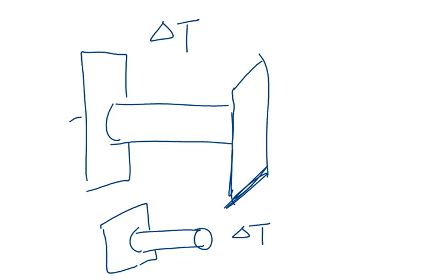And the top case becomes like a statically indeterminate problem, right? You're applying a load, a delta T, right? And even though there's no overall strain, there is deformation like in the middle, right? You just don't get an overall deformation. And then on the bottom case, if you apply a delta T, which is a load, then you end up with a strain. Okay? So now it's actually consistent with what happens when you apply a force. Right? You could either apply a force or you could apply a temperature change to get a strain.